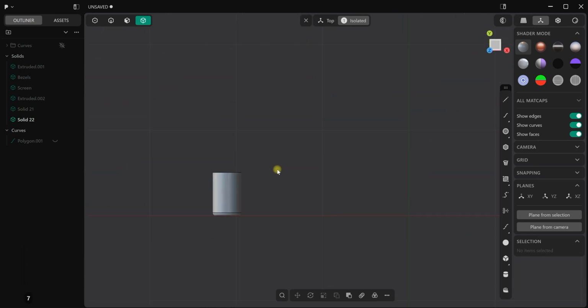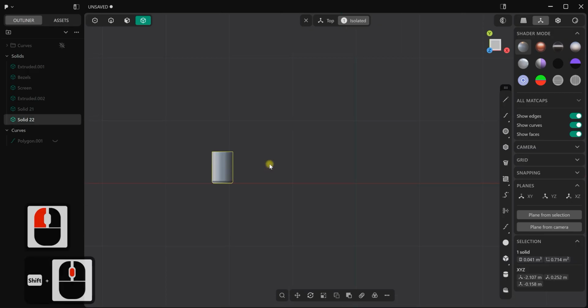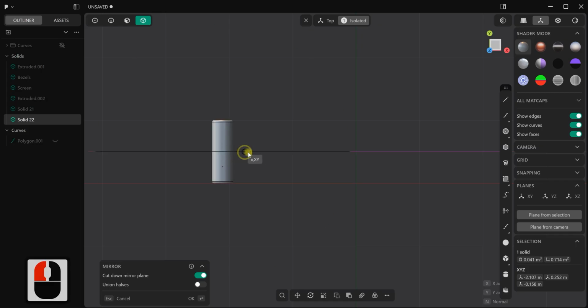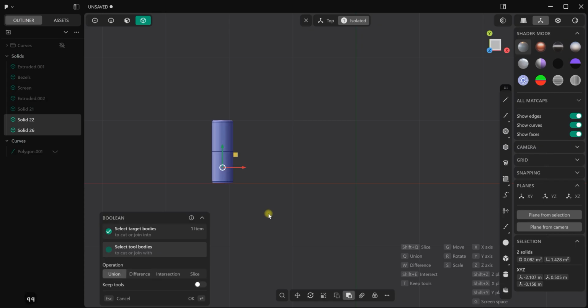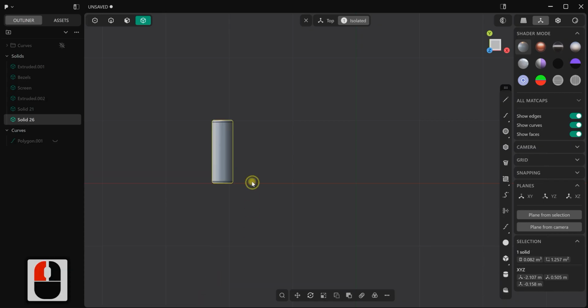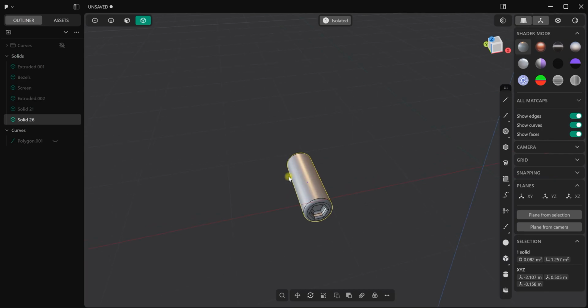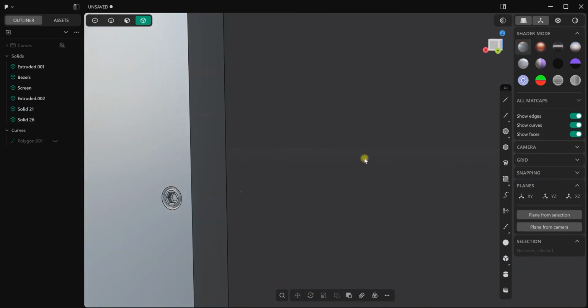or delete. Go to the top view, select our bolt, press Alt X to mirror it, then press F, click on the top of our bolt and drag the mouse to the right, press OK to confirm, then press Q and Q again to unionize the mesh. Beautiful. And press the dot to return to the project.